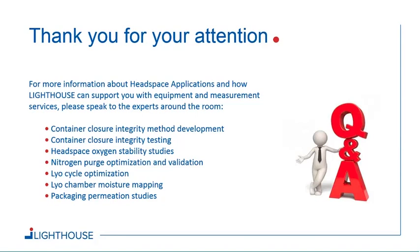The general answer is yes. The question with plastic bottles, of course, is that you will also have permeation of gas. We didn't go over this in detail in this webinar, but you can easily distinguish between permeation and an actual leak defect. And so it adds an extra complication. So with plastic bottles, you have to take this into account, but in principle, it's possible.